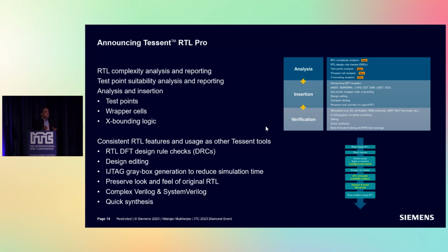It also, as I mentioned, preserves the look and feel of the RTL, which is very important. So it already does that. And we try to minimize the changes to the blocks where you are not touching. The tools are also capable of handling complex Verilog and SystemVerilog constructs in your design, things like SystemVerilog interfaces or generate loops.